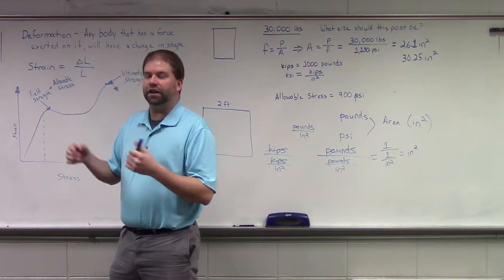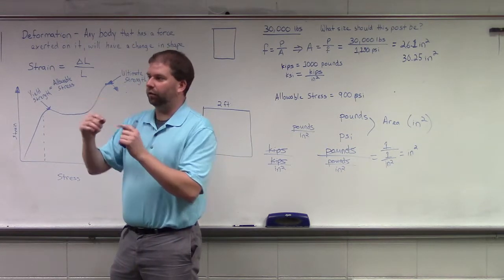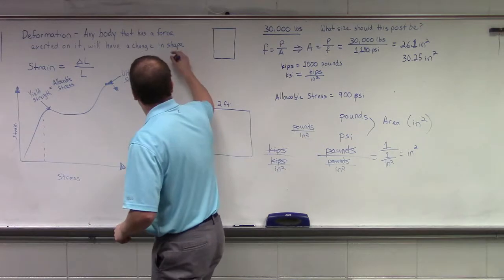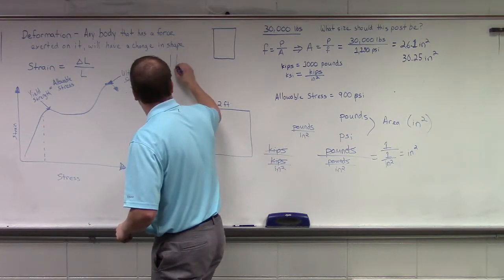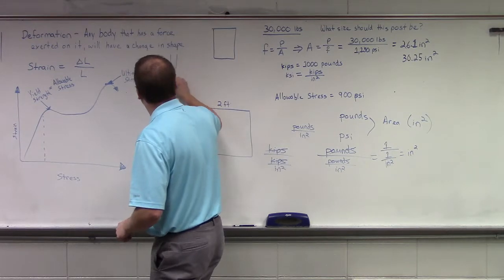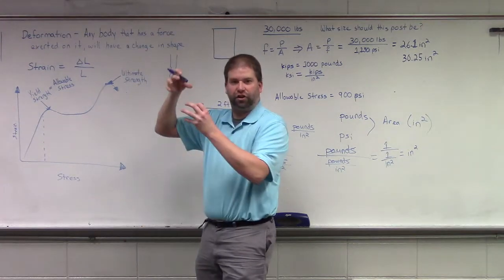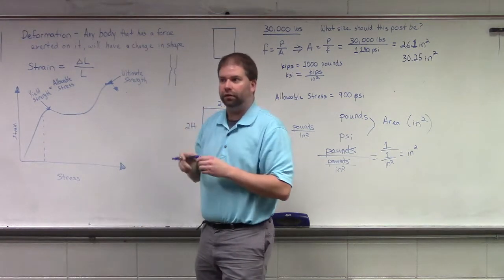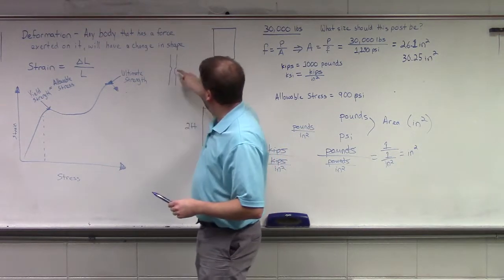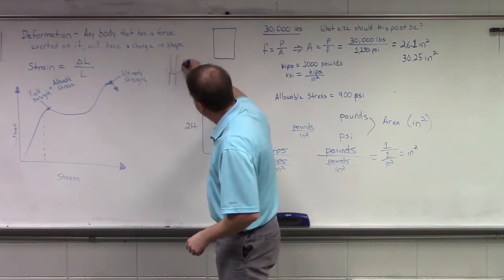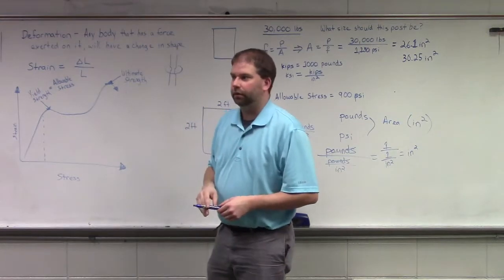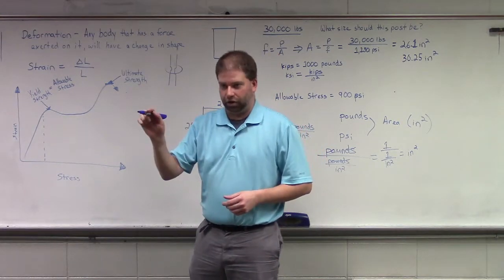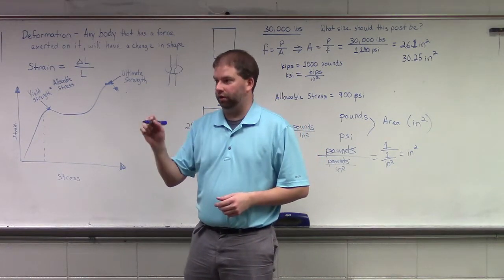What that means is it starts to permanently deform. What happens in steel is a concept called necking, where a portion of the steel itself will change shape and actually thin out. What is happening right here? It's getting stretched and it's becoming more brittle.